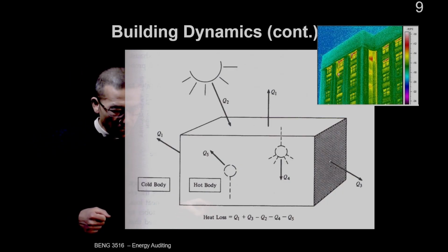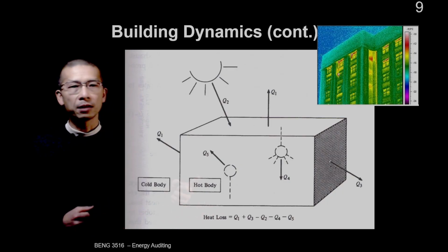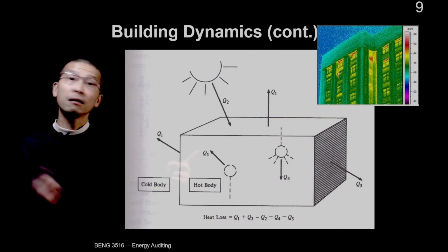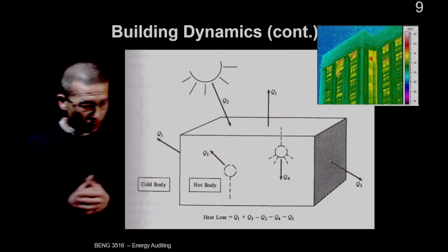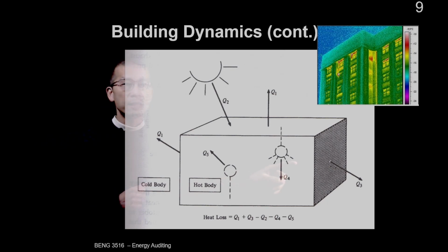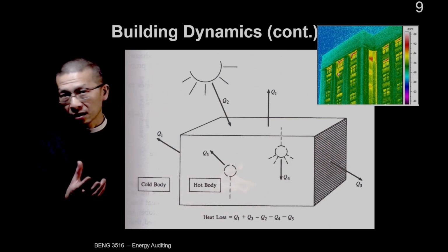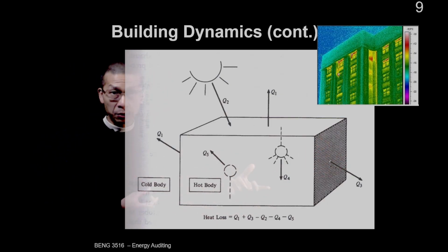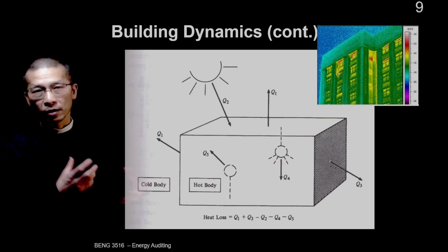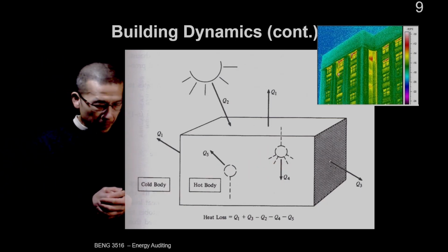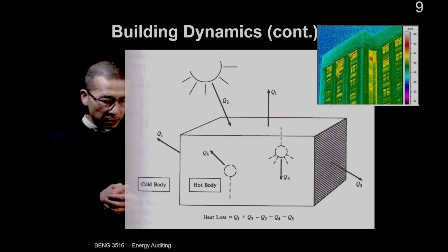So 1 and 3 are now heat loss. 1 again, thermal heat transfer, due to the temperature difference. Number 3, inside we are leaking 20-degree air to outdoors, and 0 degree, minus 10, minus 20 air comes in to replace the 20-degree air, right? So that's also energy loss there. So 1 and 3 are losses.